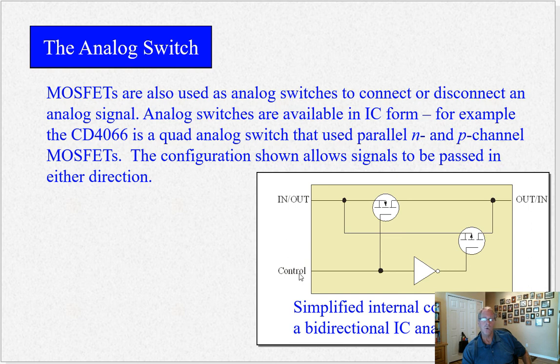And I need to control and shut off the output during power down. Okay, because during power down, bad things happen and it results in a big pop going out into the speakers. So I'm going to try to put one of these circuits into my design and operate this control using a voltage supervisor chip to shut this off when power falls below a certain voltage. Okay, so nominally it's at 5 volts. As soon as it falls below 4.7 volts, I'm going to open this circuit up, which is going to disconnect the output to my amplifier, which should, well, hopefully solve my power down pop problem, because it's really annoying. Very, very clever circuit, very common, and I'm excited. I'll let you know how it goes probably in a couple of weeks.